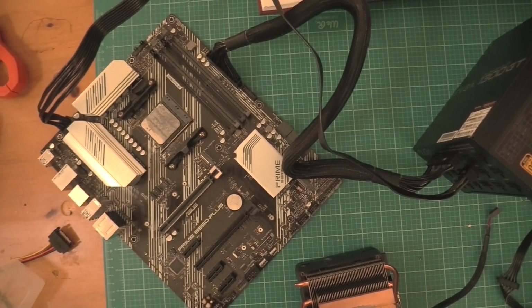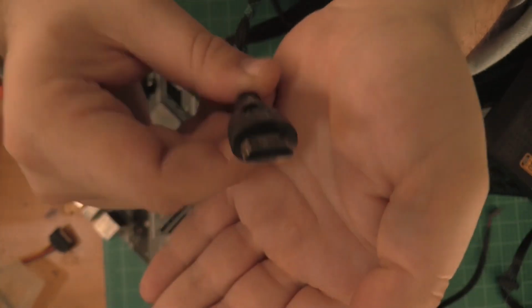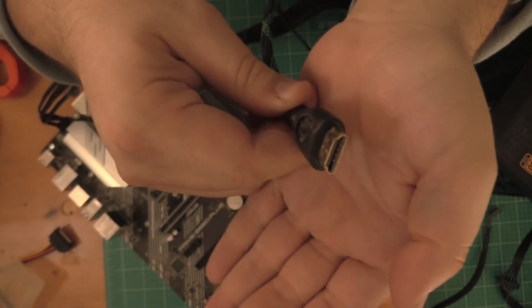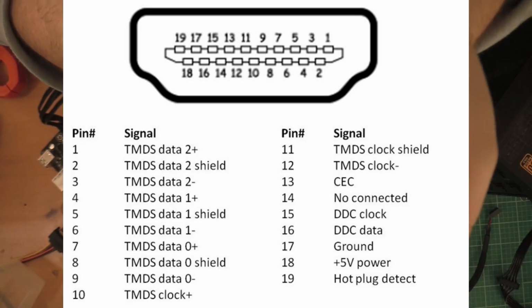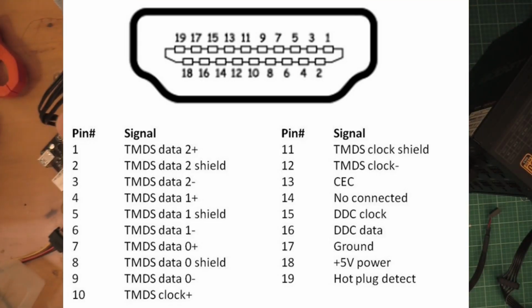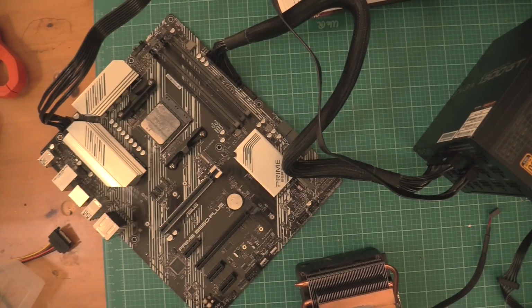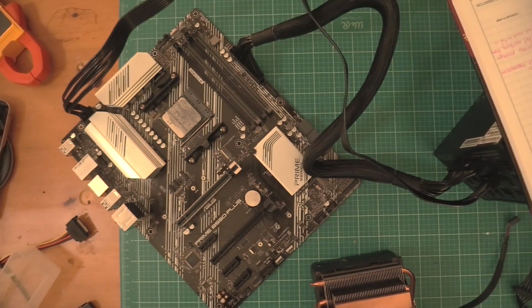HDMI stands for High Definition Multimedia Interface and has 19 pins. And those 19 pins are oriented in this connector in this arrangement. Pins 1 through 9 are more or less the video signal we're transmitting. Pins 10 through 19 are pins that control, regulate, and power that transmission. This TV accepts 3 HDMI inputs and allows us to see what the motherboard wants us to see.